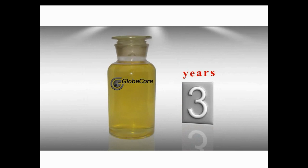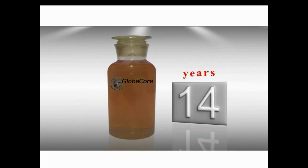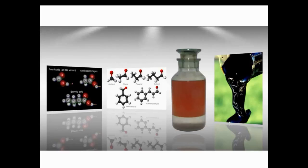The reason is a transformer has breathers. And as a transformer heats and cools, they suck in oxygen from the atmosphere. Besides, oil undergoes oxidization decay as well as paper. So, how does oxidized oil destroy a transformer? First of all, when oxidized, oil can be very simply revealed by its color. Take a sample in a bottle and you will see it is very dark, red-brown.